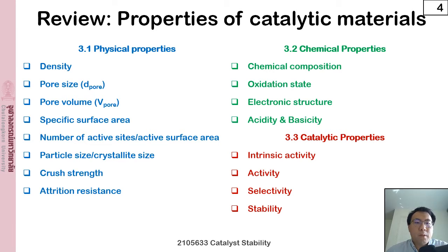After we have mentioned the surface area, some definitions make the surface area more meaningful by representing only the important part of your catalyst. As we can see in the next property, the active surface area is the surface area only in the region where you have the active site. So this one will represent the catalyst more effectively.